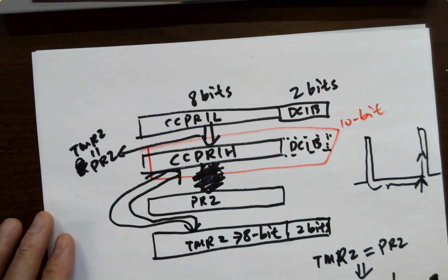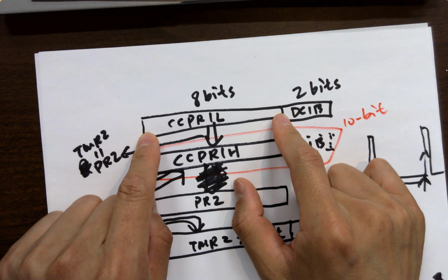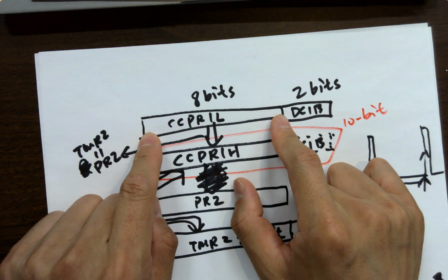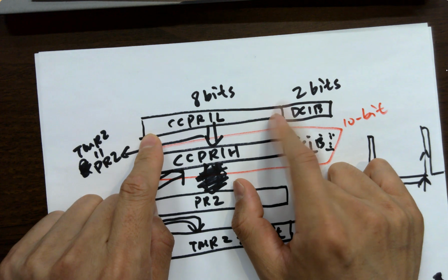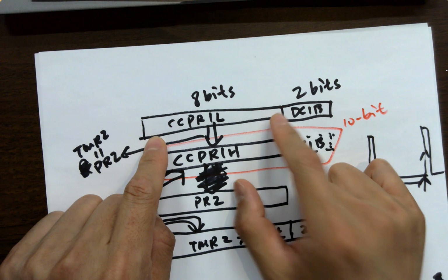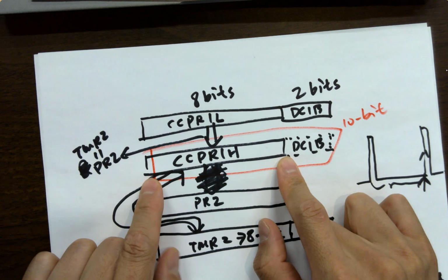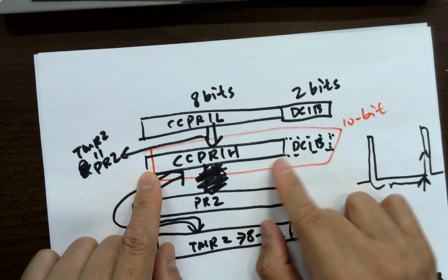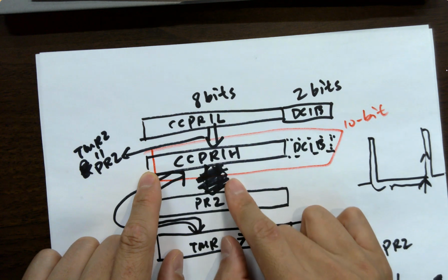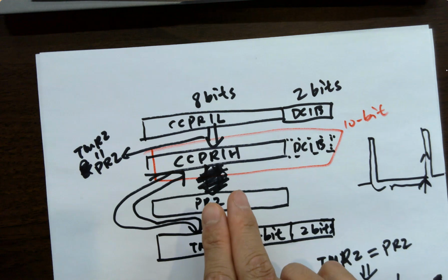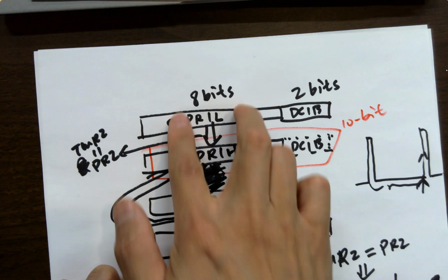Okay, this is a register that stores the duty value. It's just 8-bit D flip-flops, actually, just a register. So registers can store numbers, right? It's a latch. It can latch a digital value in there, no problem, right? This is also a register. It's a higher byte version of it, serving similar purposes. However, we don't have to know the details. They are both 8-bit registers.